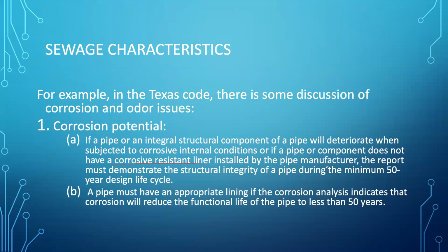Sewage under the right conditions is so corrosive that a 6 or 7 inch wall thickness of reinforced concrete pipe can be degraded and deteriorate in a matter of just a few years, 10 or 12. So that 50-year design life is all of a sudden a long time.